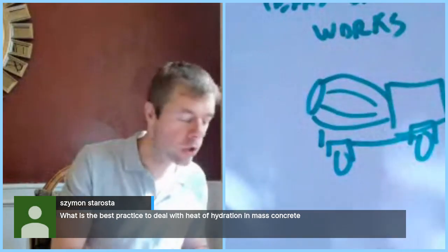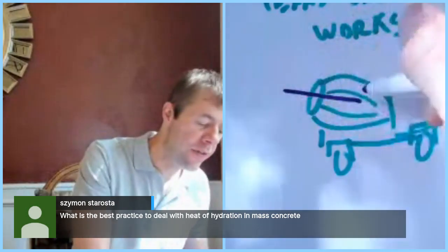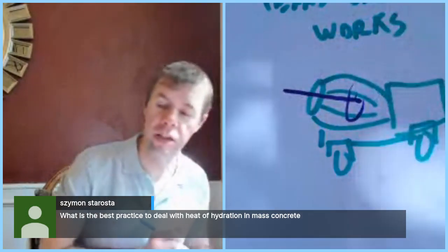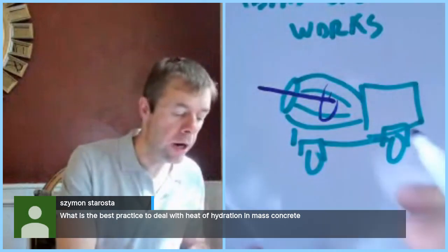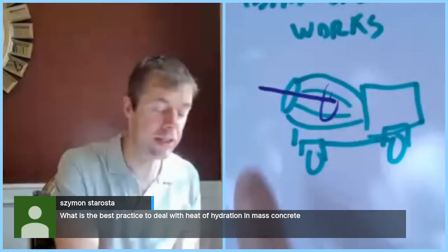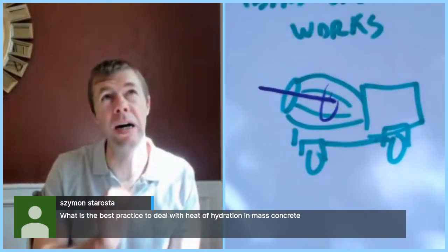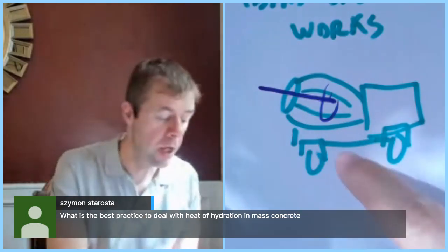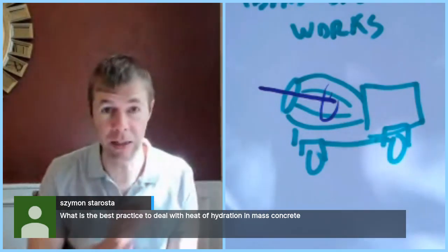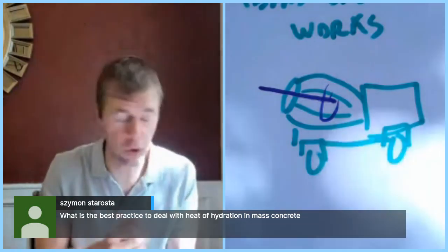In the concrete truck itself, they actually have a wand that goes inside and sprays liquid nitrogen. You can look it up. It cools the concrete down. It's totally amazing, and it's very inexpensive once you get it set up. It's widely used in Texas, New Mexico and Arizona. That is an amazing tool to cool concrete down for summer concreting or mass concreting.